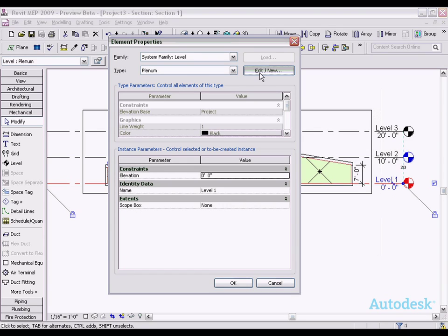But this is just an example of how this functionality works. In general, with a scenario like this, you could just leave it as automatic and it would work properly. Just an explanation of how the automatic calculation works. Let's go ahead and set our type back to automatic. It assumes a 4-foot default height, and it will use that 4-foot calculation height here in this 7-foot and 5-foot high roof scenario. And the reason why is because the bounding walls for this room extend beyond the 4-foot level until they are cut by the roof.